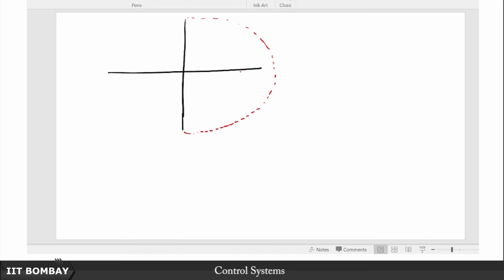In root locus analysis also we said that if you consider all infinite poles and zeros, then it is a biproper system. If you have n poles and m zeros, then there are basically n minus m zeros at infinity. That is how the asymptotes go around, right. So we do not care about these infinite ones, but there is absolutely no guarantee that you will not encounter trouble elsewhere.